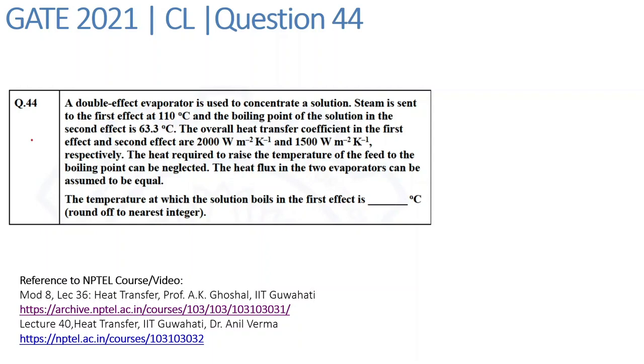So here we have been given a double effect evaporator, and we have been asked to find the temperature at which the solution boils in the first effect. So basically we have been asked to find the outlet temperature of the vapors of the first effect. Okay.